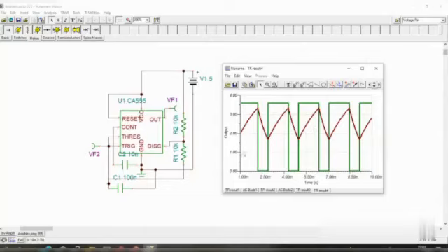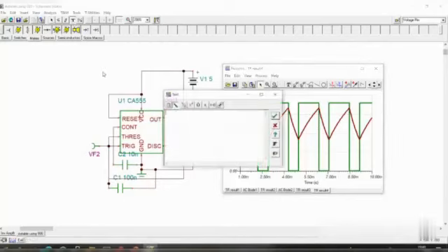The diode goes in between the discharge point, across this R1. If you put a diode across this R1, it can be made symmetrical, because I have asked you to do both the asymmetrical and symmetrical. This one is with the duty cycle not equal to 50%. So go to the text and put the name. This is actually asymmetrical astable multi.